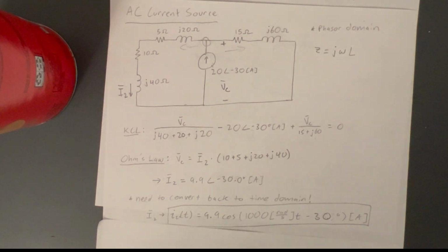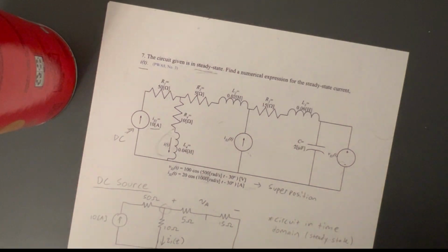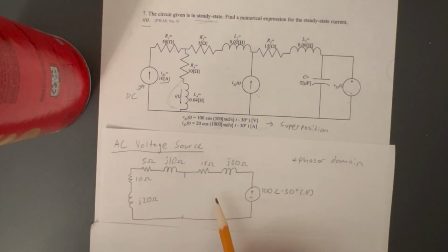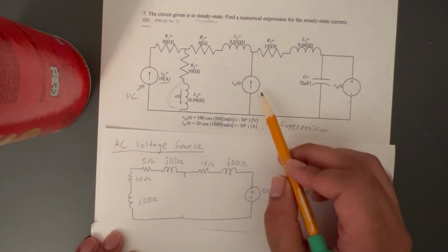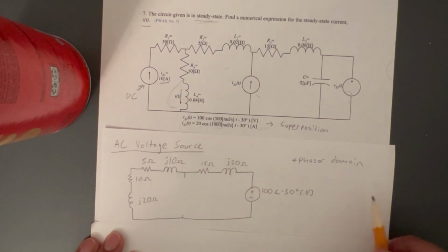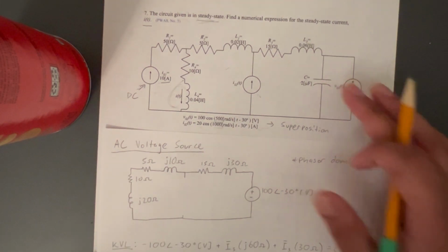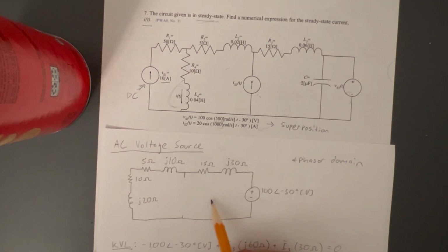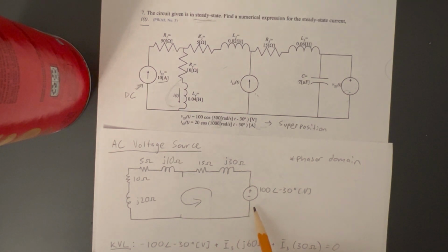So now we need to solve for our final source, which is our voltage source. Okay, so I've gone ahead and redrawn this. As before, this source is open circuited, and so is this one. As you can see here, everything is just in series, so we only really need one equation for this. I've done that here. This is going around the loop this way, going up to the negative, right there. And then this is all one current that's flowing throughout the whole thing.